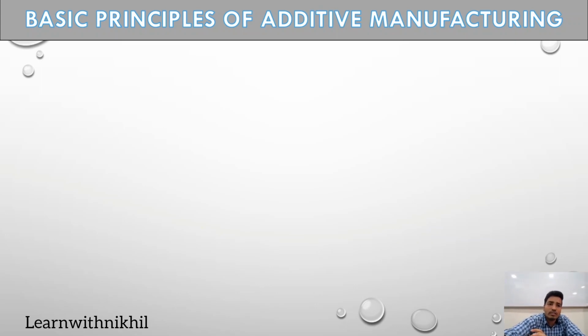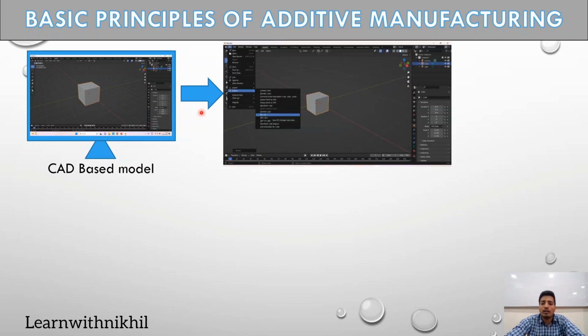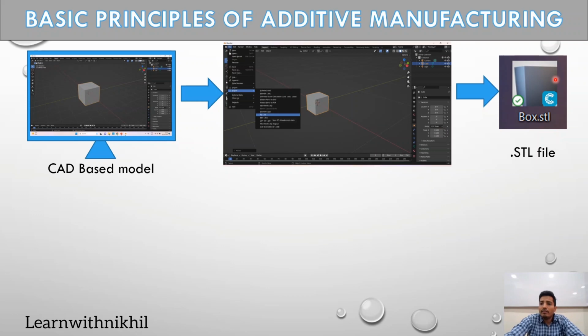Next, moving towards the basic principles of additive manufacturing. We have already studied this in chapter number 1, but you will just revise it in short. Firstly, we have to make a 3D object. Whatever object we want to make, we have to prepare that CAD model. For this CAD model, again, you can use any CAD software, as we have seen in our previous slides. This is the screenshot of Blender, where we are making a cube. Then we have to export it into STL format, and we get this type of STL file. You have to save it on your PC.